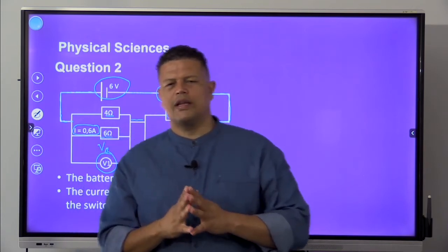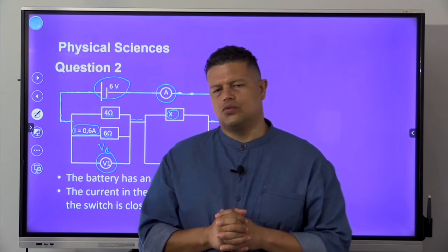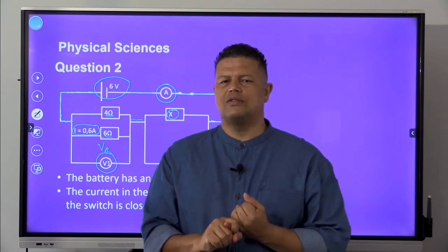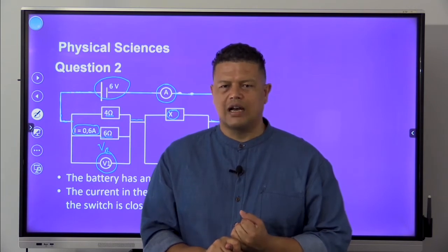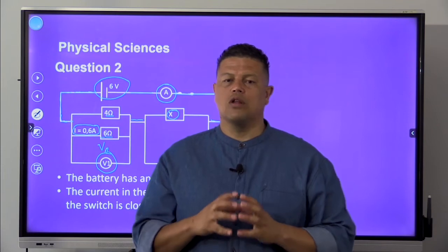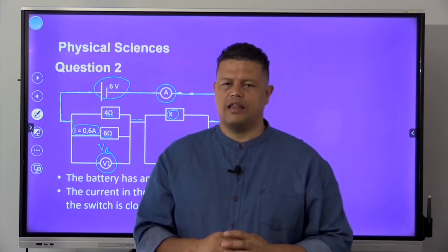So let's quickly just talk about strategies that I like to use. The first thing is you must always try to find what is the total current of the circuit. I believe if you've got the current of the circuit, you can literally calculate anything.